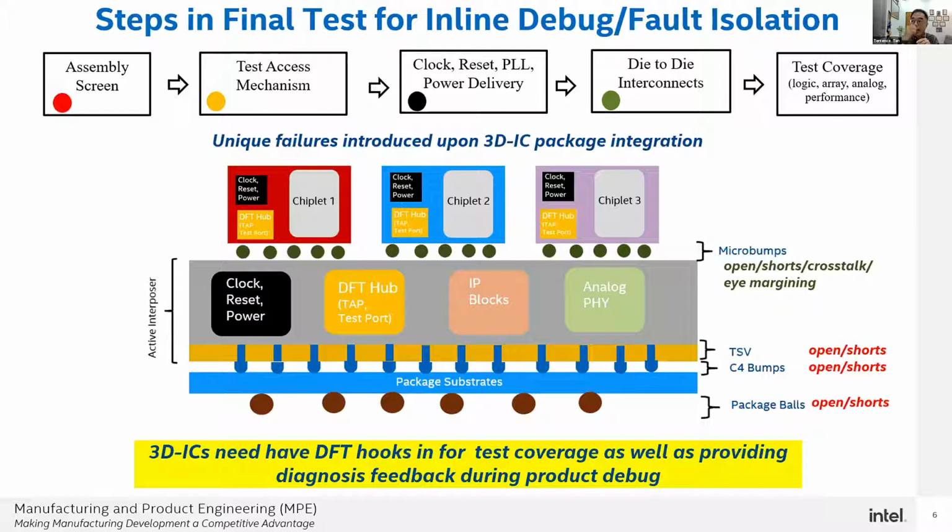So your repair mechanism probably needs to be smarter. You need to have a repair mechanism, right? It's more to overcome the yield. The way you access your chiplet is still going to be the same, because it's still die to die. But you need to have a way to screen the assembly and probably to recover yield through a more robust repair mechanism, and have a way to detect things like crosstalk, which is very important. This is how I see it changing when you go from micro bumps to hybrid bonding.